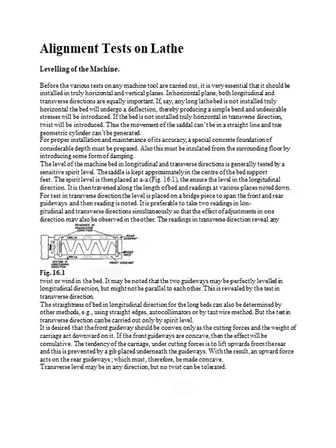The spirit level is placed longitudinally and crosswise. Longitudinally, if there is any variation in the level, it will cause bending. Transversely, you have to check, otherwise there will be a twist or wind in the bed. So for both of these we use the spirit level.